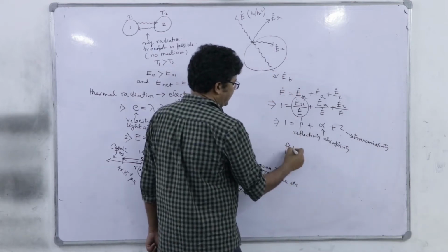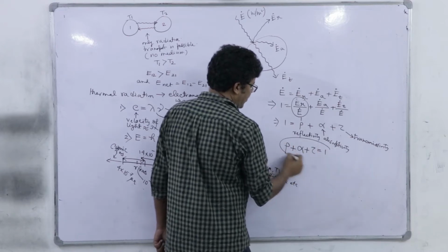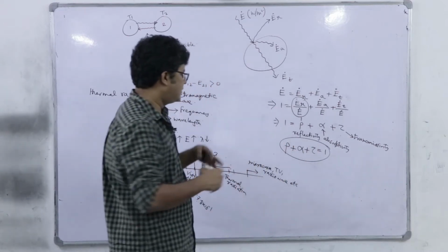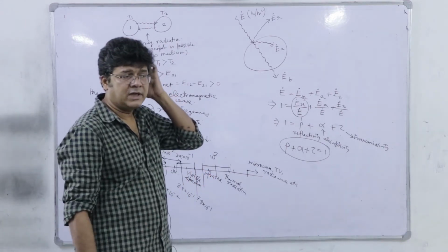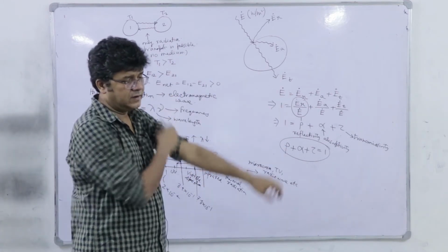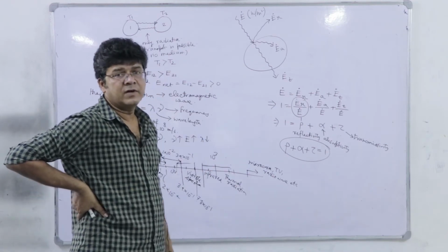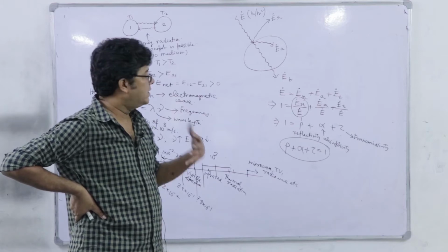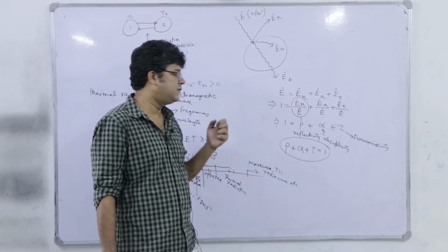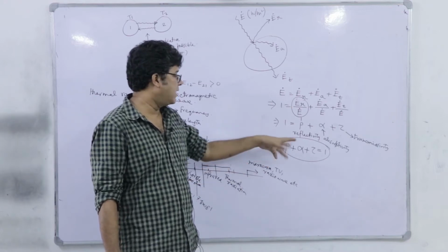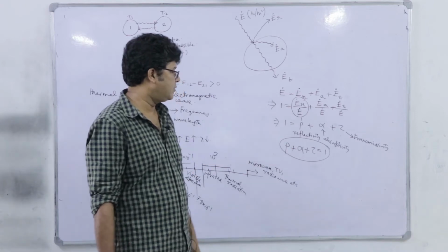So, we can write reflectivity plus absorptivity plus transmissivity equal to 1. Mostly what we deal in reality are the opaque systems, where the transmissivity is 0. So, reflectivity plus absorptivity is equal to 1, and the visual appearance of color is actually an interplay of this reflectivity and absorptivity.